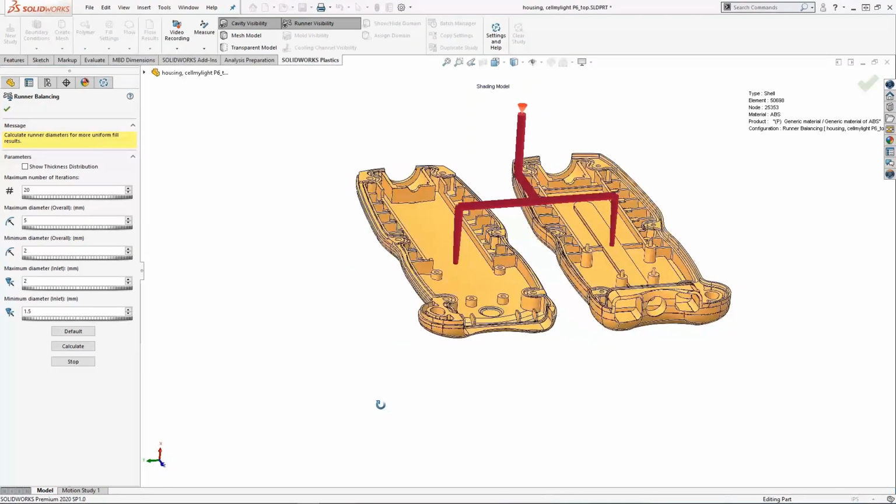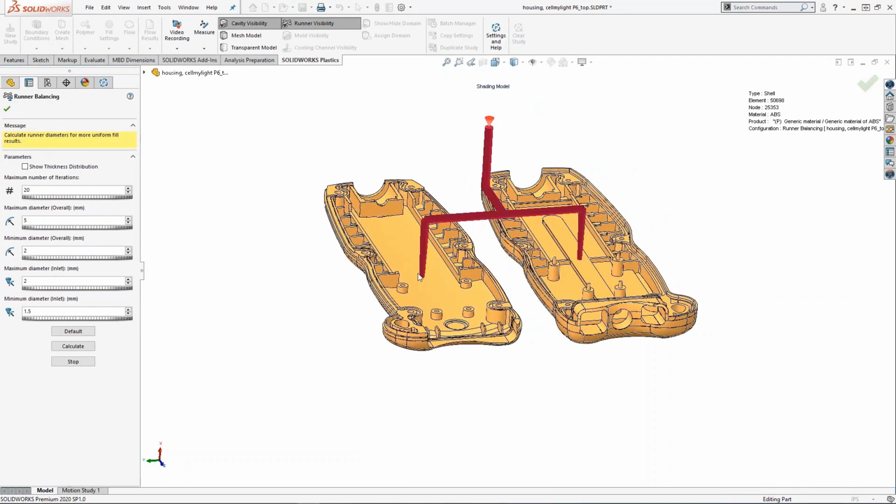Previously, as you've seen, when I set up the runner, these three sketch entities were just 3 millimeters start and end. There was no tapering. The only taper I had was for these two entities that actually go into the cavity, into the mold. And this I had a draft of, it goes from 3 millimeters down to 2 millimeters, and it was the same on both ends.